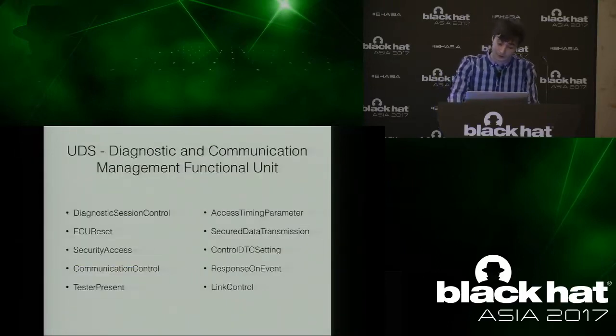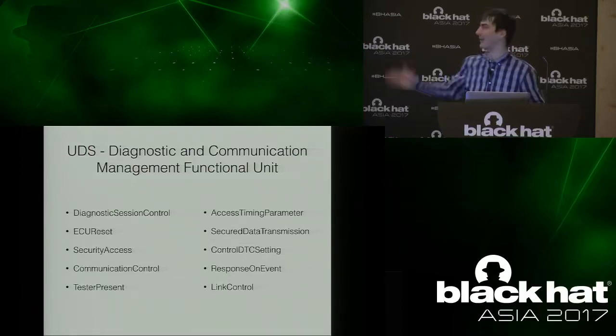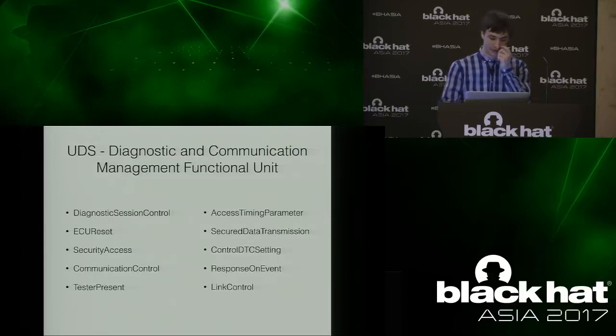This is the first functional unit, and I am going to try to make this as exciting as possible while having a big list on the screen. Basically, I'm going to go through why these are actually interesting to security folks. We'll start with diagnostic session control. This one is really just a prerequisite for many things. So often you'll have to move a controller into a diagnostic session or a programming session or something like that, which just puts it in a special mode where it might disable certain features because it knows you're going to perform diagnostics. It's also used sometimes to access the bootloader when you're programming.